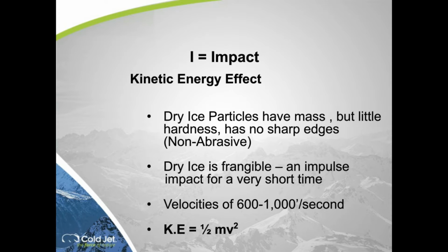So this is where you're going to get the biggest bang for your buck, where you make your adjustments in your velocity controls on pressure to control the kinetic energy and your particle size. Even if you choose to use a 3 millimeter, you're able to knock that down with splitters, sometimes called fragmentation. You can knock down that particle size with some pins inside the nozzles that allow you to reduce the kinetic energy. Helpful when you get on a substrate that may be gentler.